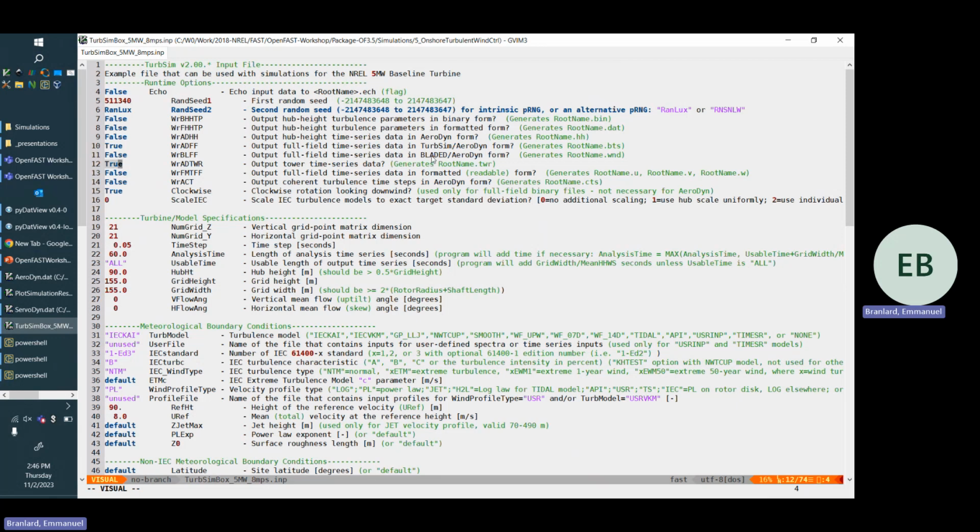My way of doing it is different folders. I do a parametric study within a folder, so I have different FST files in one folder, I compare the different FST files within that folder, and I keep the output files there. After I'm done with the project, I delete all the output files and keep the input files. I personally delete output files when it's been a long time. You don't want to keep all this data, right?